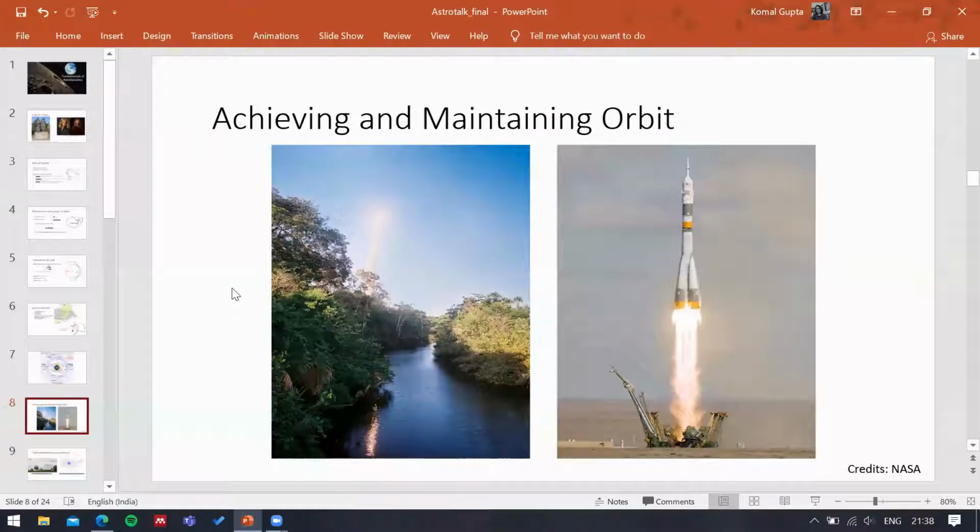So the amount of energy also depends on the location of the launch site, which is why most launch sites are placed close to the equator. For an orbit with low inclination, we can use the Earth's rotation to pump some extra energy, and for that reason, polar orbits would usually require more energy than orbits of less inclination.